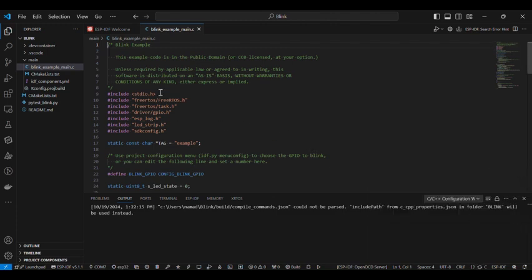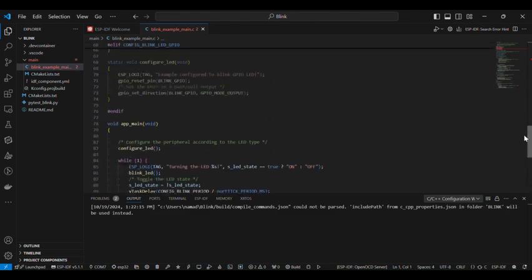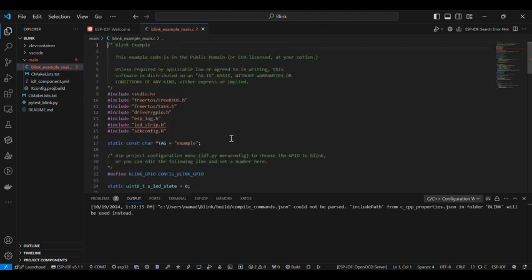As you can see, this is the program for the basic LED blink. Inside this program, they have declared a lot of header files and a lot of inbuilt code to access that LED very easily. Normally every program has stdio. Then we have declared FreeRTOS task. Then we have declared gpio.h. Inside the driver folder we have gpio.h, which means general purpose input output header file.